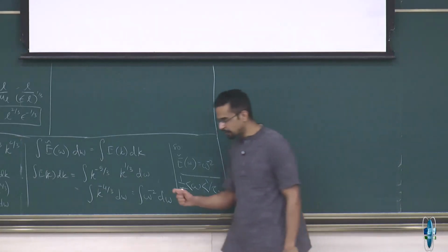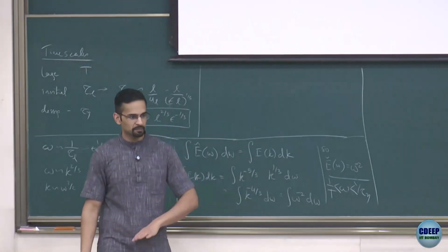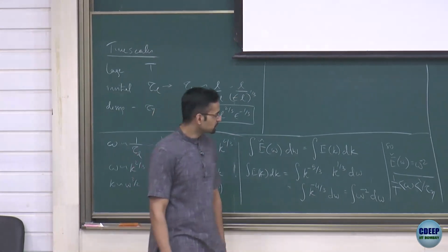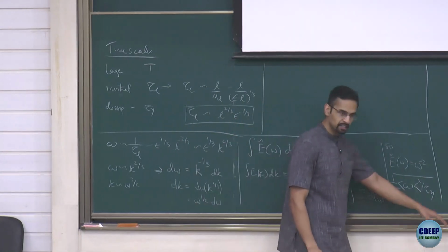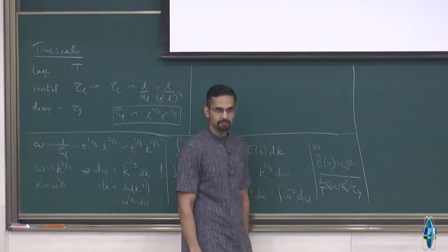So this means if I go to small enough time scales, the flow doesn't decorrelate. It will become almost constant. Things won't change much. So this means the flow is clearly not delta correlated in time. It's actually well correlated once the time goes below the Kolmogorov time scale.